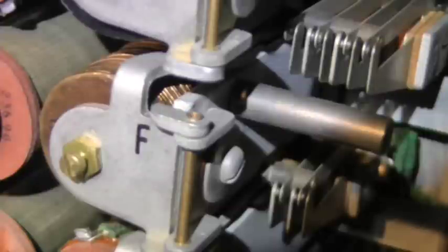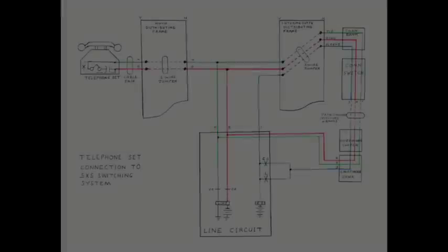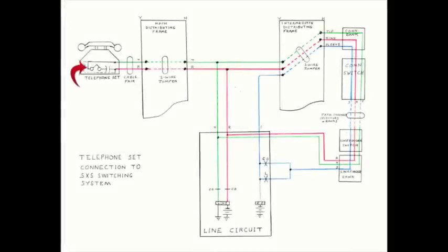The current from the ringing generator passes through the 200 ohm primary winding of the non-operated F relay. It flows through the tip and ring wipers onto the bank terminals and out to the telephone set. At this point, the only path through the telephone set is through the ringer capacitor and the ringer coils. The handset is resting on the switch hooks, and so there is no loop through the telephone set. So only the AC component of the ringing current is flowing. The DC component is blocked by the capacitor.